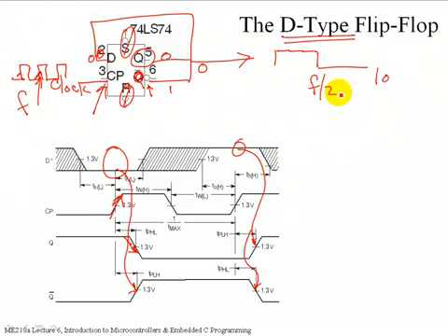If you're going to design, folks, I'm not going to have you designing with these things, but you're going to see these function blocks in functional schematics that describe the behavior of the subsystems in the microcontroller. And so you need to be able to look at these symbols and say, okay, I see how that's going to behave. And if this was falling edge triggered, there'd be a bubble on the front of that input. And in fact, technically, for it to be edge triggered, there would be a little angled bracket indicating that it was edge triggered rather than level triggered.